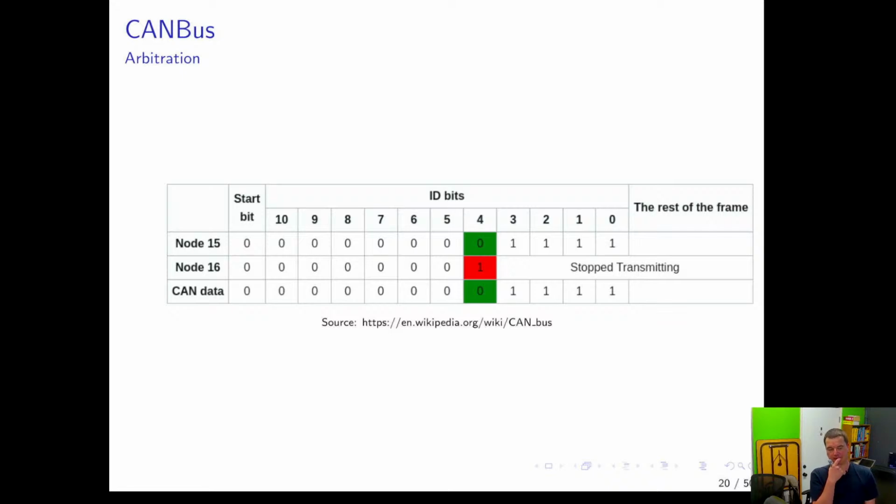And then it stops transmitting. It's the responsibility of all of the senders to monitor the bits. So that's basically how it works. And you're basically depending on everybody being well behaved. And this is mostly true. CAN is very old and the controllers are fairly stable. But still, you're actually depending on a device not misbehaving.